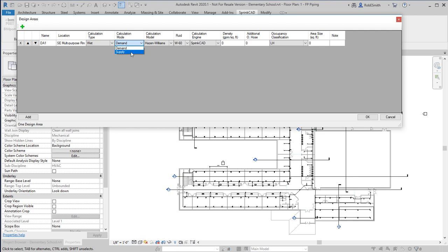A supply calculation is one in which the program takes advantage of the full force of the source point, and it will tell you this is how much fluid, water, whatever will exit out of your open fire sprinklers or standpipe outlets or fire hydrants based on the pressures available, based on the pipe sizes, based on the elevations, based on, again, the number of open flowing outlets.